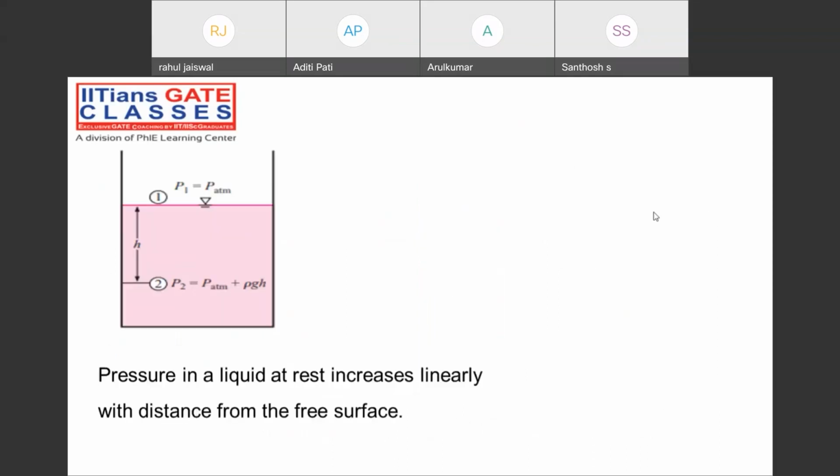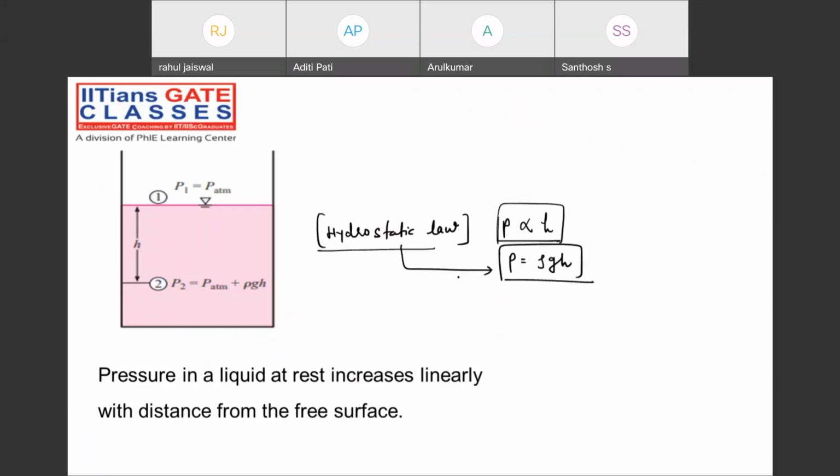No. Just note down. Anybody know about the hydrostatic law? Hydrostatic law says that the pressure in a liquid which is at rest increases linearly with the depth from the free surface. That means the pressure will be directly proportional to H. Pressure will be equal to what? Rho G into H. That is the hydrostatic law.